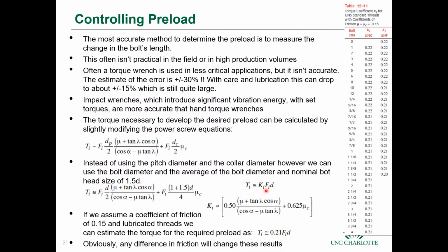be applied. So when you see torque specifications, somebody went through this analysis and said, okay, well, this is the preload that I want in that bolt, so this is the torque that I want you to apply to that assembly, so that I have that preload in the bolt. Okay.